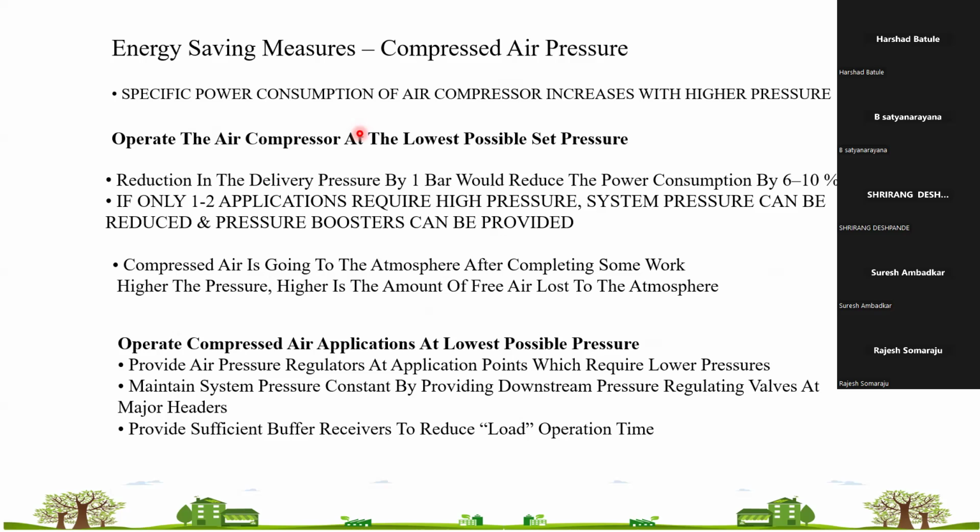Let's say a 300 TR chiller is there, and your cooling tower is around 420 to 450 TR. So your 450 TR was first utilized by your chiller, but now you are adding more load from the compressor to that cooling tower. The cooling tower cannot perform more than 450 TR, because it was designed for 450 TR. So your basin temperature goes on higher side, and both performances suffer. Your chiller is affected, your compressor is also affected.